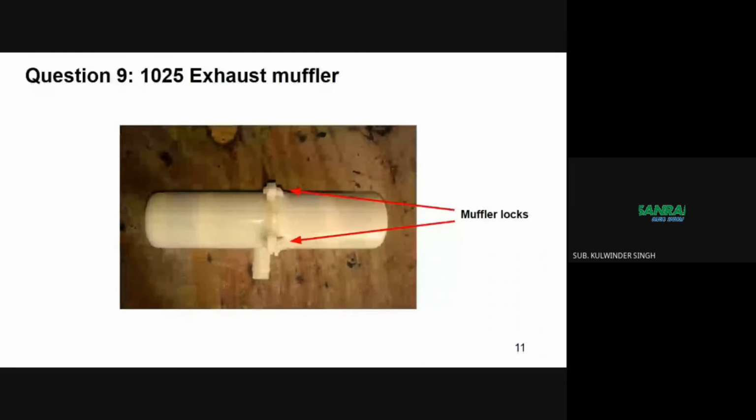There is a possibility that the zeolite may have entered the muffler through the rotary valve, as you can see in the graphics. Open the muffler by clicking the locks available on it, as shown in the graphics. Wash the filter inside the muffler with soapy water and rebuild it after proper drying. Now reassemble the muffler, rotary valve, and sieve bed to the machine and check the functionality.